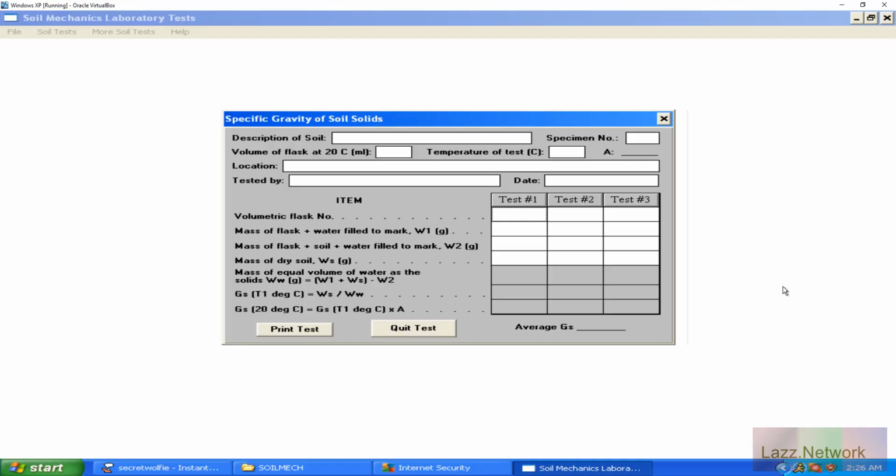I'm guilty of it, because if you dry out your peat or your organic soils, it's pretty much going to become charcoal. And then when you try to do a test like this, most of your materials are just going to float, and the water absorption to get in there to find the specific gravity or the exact density of the material itself isn't really going to work, because when you get that moisture out, you can never get it back in again.